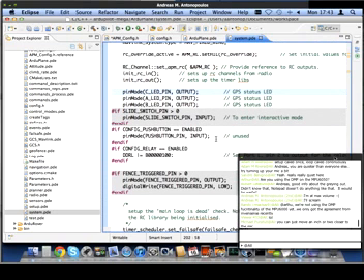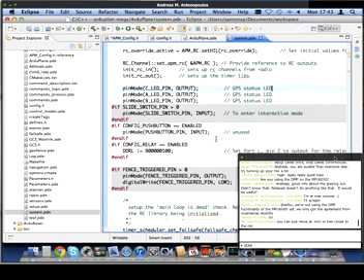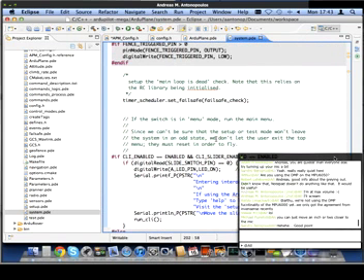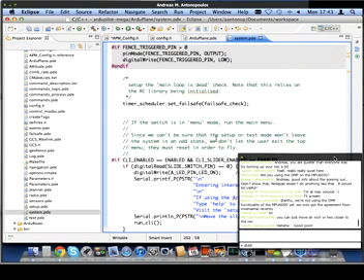We set up the various radio controlled channels. So we set up the PWM inputs and outputs, and set up the LEDs, so you get those fancy LEDs. We have to set them as outputs so that you can then turn them on and off later.